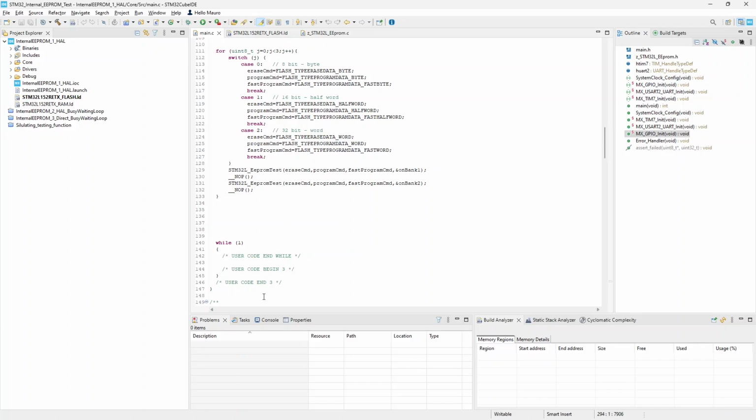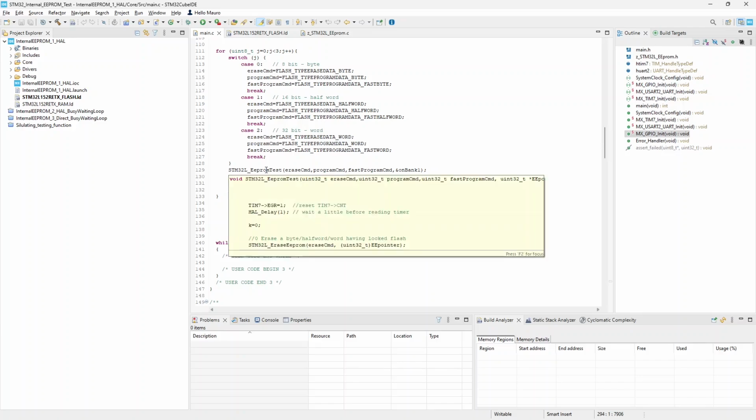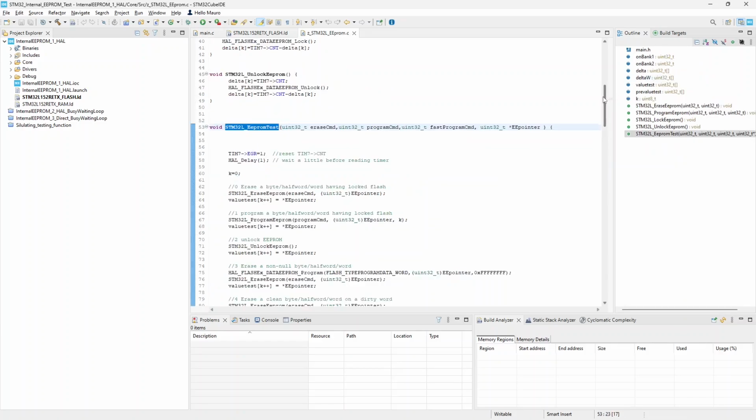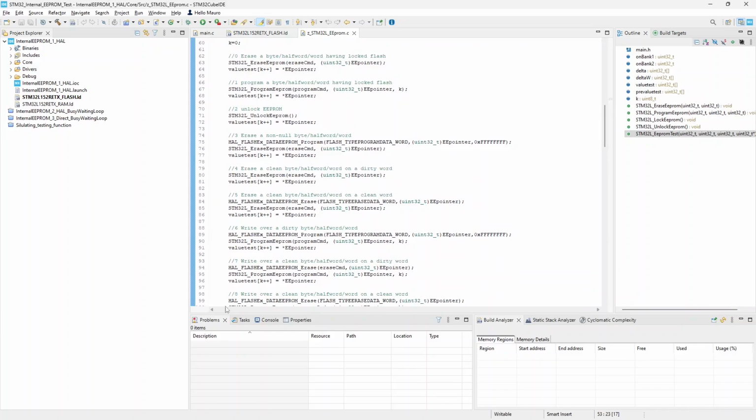Be aware to avoid putting this kind of test, writing EEPROMs, flash, or other heavy or destructive operations, inside the main loop, as if the test goes out of control for any reason, it can quickly burn out devices, chips, and so on. Test function performs this series of operations, measuring timings and results.